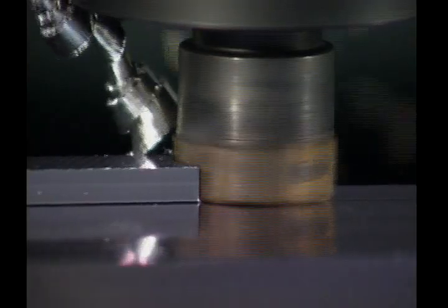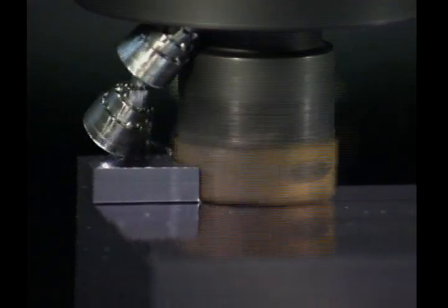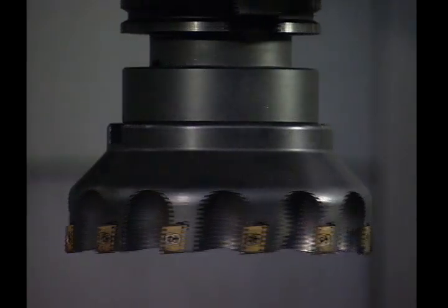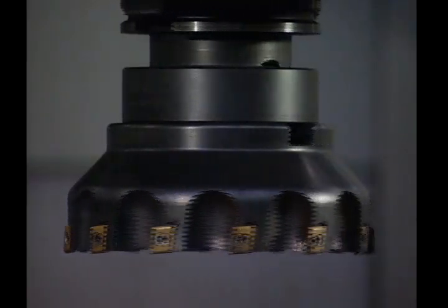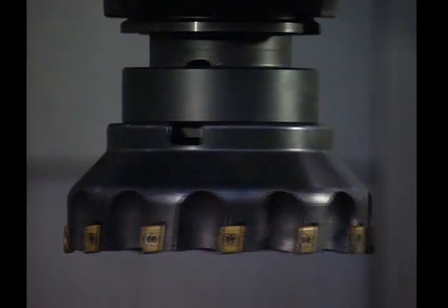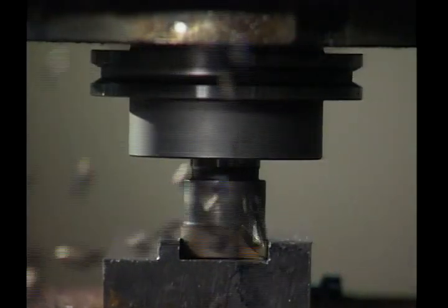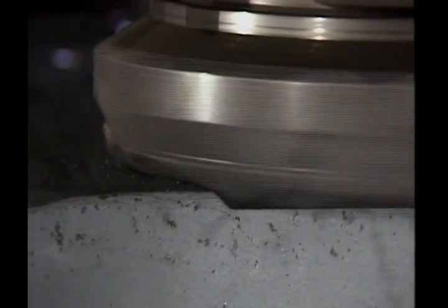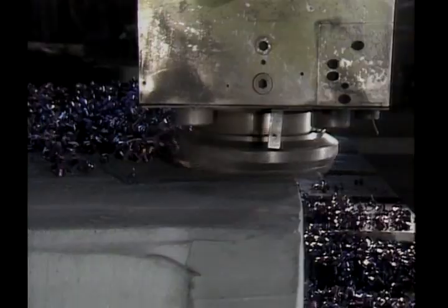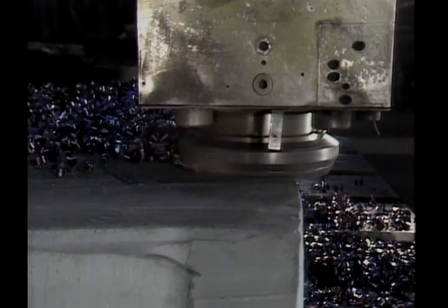Face milling cutters effectively generate flat surfaces with the spindle perpendicular to the work surface. The cutter body has multiple pockets to accept a variety of indexable insert types. As the cutter rotates, each insert edge alternately enters and leaves the cut, removing a small amount of material in a short, discontinuous chip. The chip thickness at the start of the cut is called the undeformed chip thickness.